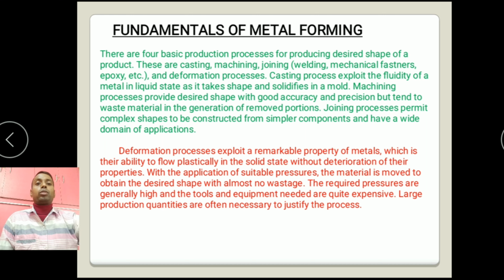But what is deformation process? Deformation process exploits a remarkable property of metal, which is their ability to flow plastically in the solid state without deterioration of their properties. Very important thing, and keep in your mind my dear friends, without deterioration of their mechanical properties and thermal and all the properties. With the application of suitable pressure the material is moved to obtain the desired shape with almost no wastage.